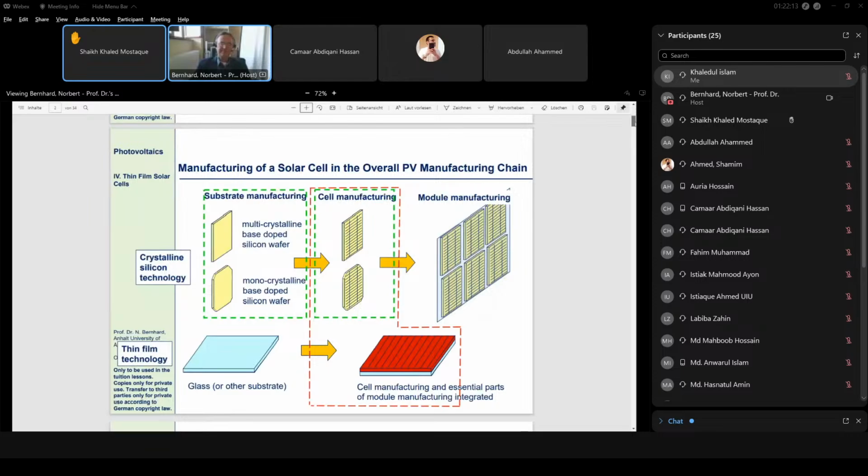Next one. Okay. Where it has been said that to make a solar cell we need to use direct or quasi-direct semiconductors, but not the indirect semiconductors. Could you please explain why? Yes, because an indirect semiconductor is absorbing too weakly. I mean, just a material of a few micrometers would not be sufficient to absorb sufficient light.